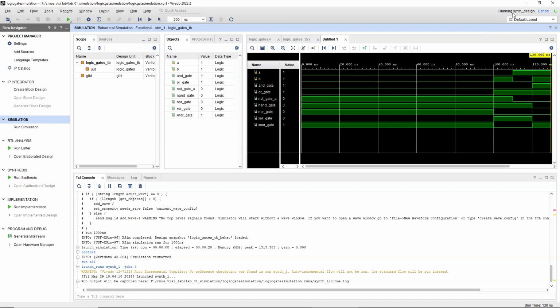Through timing analysis, Vivado ensures your design will operate correctly at the desired clock speeds. Early in the design phase, synthesis detects potential errors, allowing for timely corrections. A netlist is created, outlining how each component in your design connects, setting the stage for physical realization. Vivado synthesis applies power optimization techniques, making your design as energy efficient as possible.